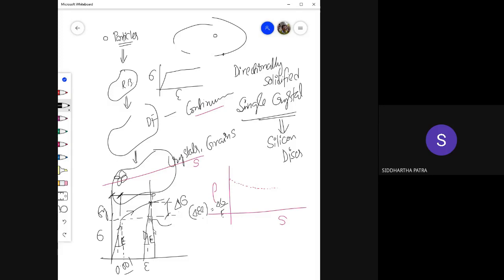That means a total of this much is unloaded, which is sigma at P divided by E. And if the total strain at P is epsilon, okay, I shouldn't be calling it epsilon P. So epsilon P is the plastic strain, and that is this total strain minus whatever is elastic, because that is the part which could not be recovered.